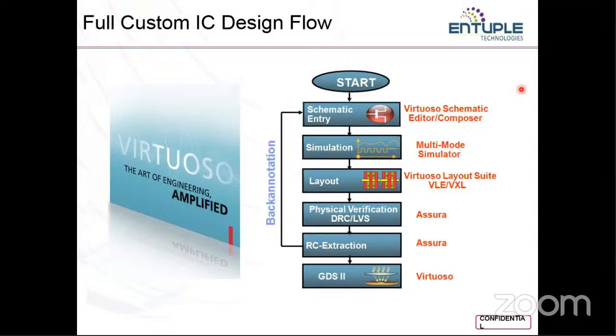So because of these things, the dimensions, certain components get generated automatically, like a resistor, a capacitor, a diode, bipolar junction transistor, an inductor. For example, if you have a path segment that is connecting two terminals of two different components, and if it is of higher width, then obviously the resistance increases. The resistance provided by that path segment increases.